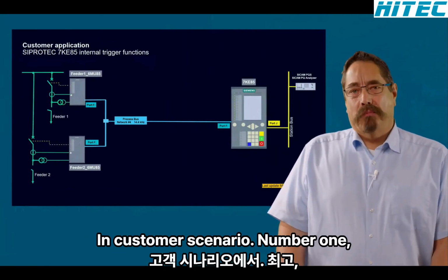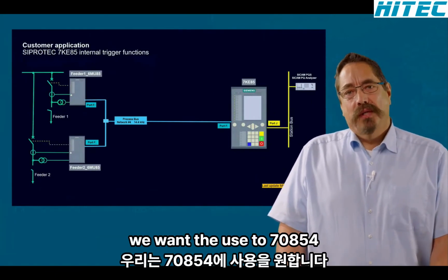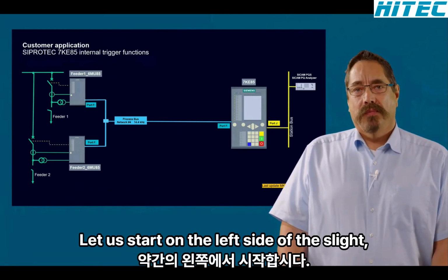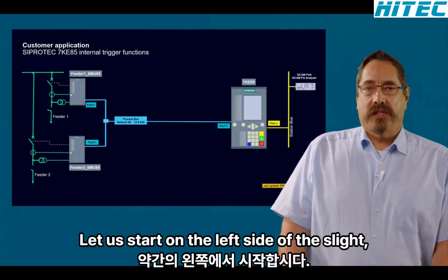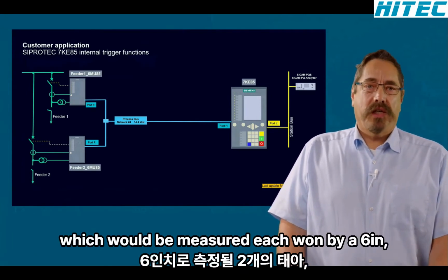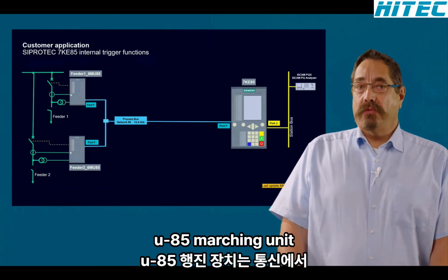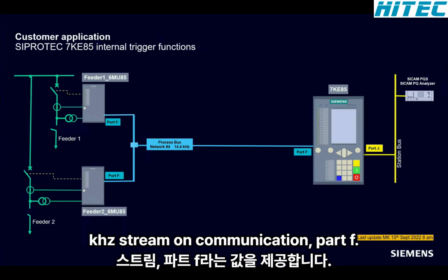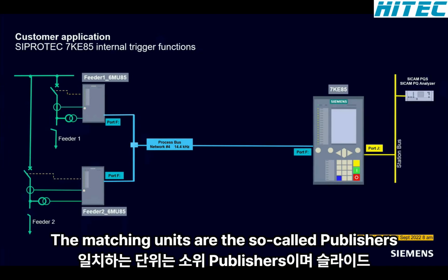In customer scenario number 1, we want to use the 7KE85 fault recorder internal trigger mechanism. Let us start on the left side of the slide. Here we can see 2 feeders, which will be measured, each one by a 6MU85 merging unit. That merging unit provides its sampled measured values, called SMV, in a 14.4 kHz stream on communication port F. The merging units are the so-called publishers.